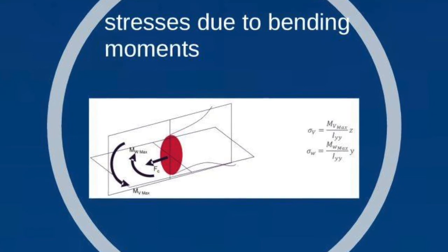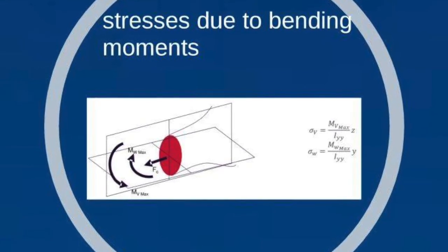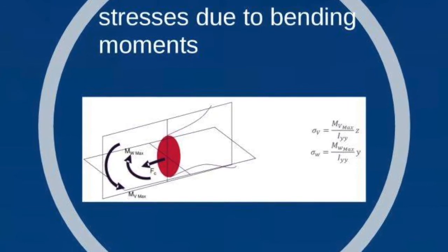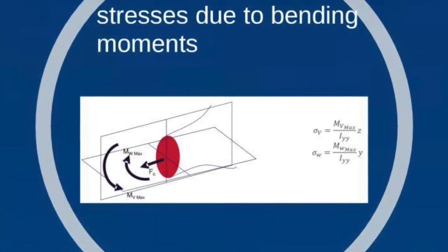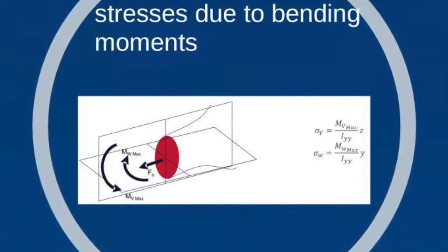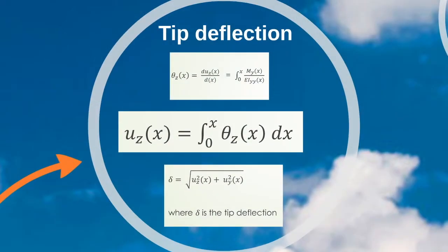stress. The total stress experienced by the blade is then the sum of these stresses and the centrifugal stress. This was then compared to the yield stress of PMMA and was found to be reasonably lower. Finally, we calculated the tip deflections so as to make sure we didn't have excessive deflections of the tip, since this is the area with the highest centrifugal stress. The tip deflection was found to be 1.9 mm, which we agreed was a reasonable value. We decided to have a safety factor of 1.6.